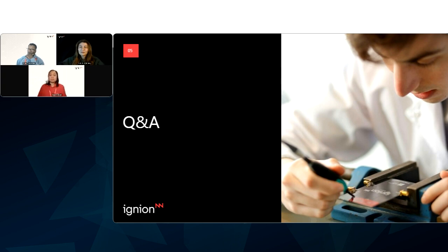Yeah, sure. This is more of a general question. Since it's pretty general like that, I would say there's no simple, hard and fast rule to antenna matching necessarily. But obviously, increasing your L and C, meaning your inductance and capacitance, typically lowers the resonance, and decreasing those, whether it's in shunt or series, depending on what matching network topology you have deployed on your PCB, would shift the resonance to the right.